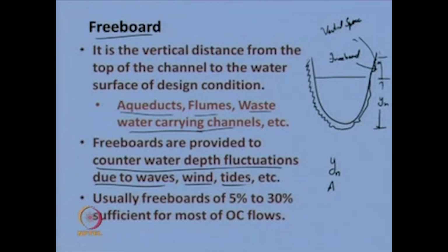Usually, the freeboards are applied up to 5 to 30% in most uniform flow. Most of the channels you can design from 5% to 30%. So, this height is around 5 to 30% of the normal depth of the design channel. So, that is sufficient in most of the cases.